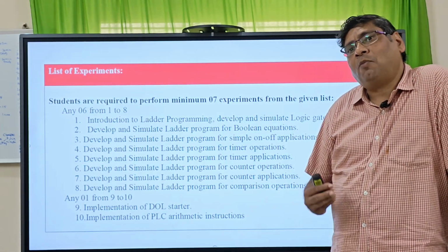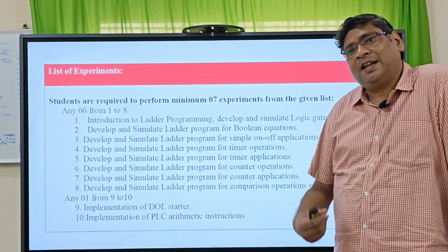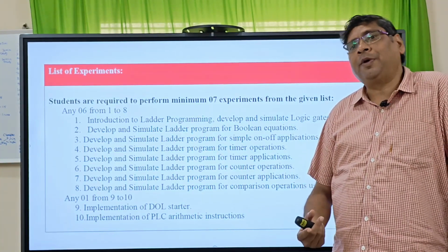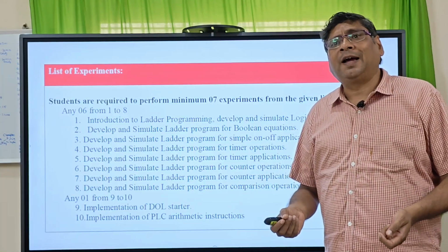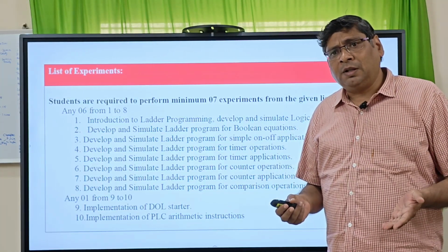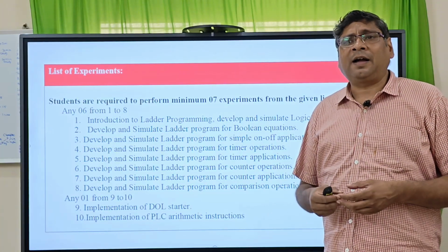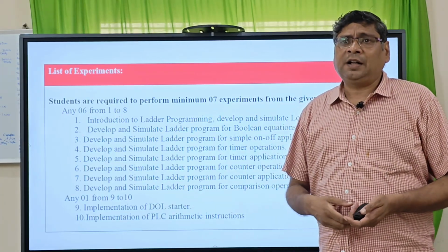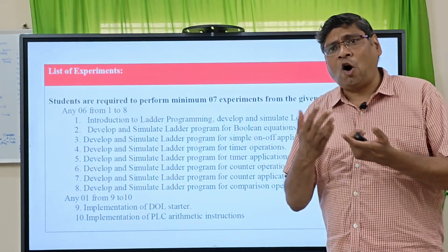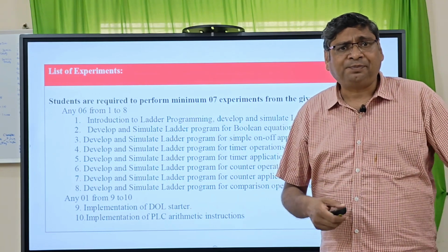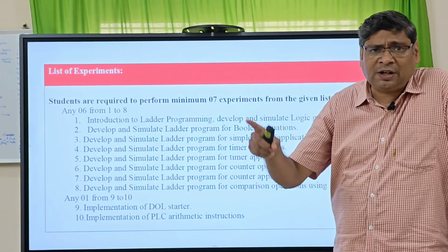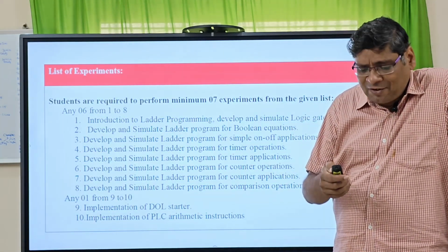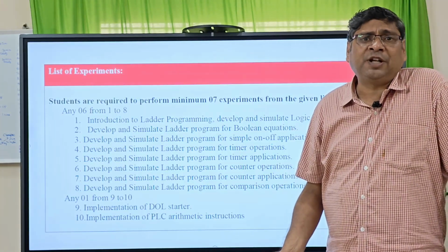We learned what model of PLC hardware you have, and the name of the manufacturer or OEM of that PLC. Then we saw RSLogix, how you open it on your computer, and how you open the program. Then you go to the ladder diagram, where you put the NO, NC and the coil. After that, how you do input addressing, output addressing, coil addressing, and how you use coil latching. We also saw all the 7 gates and the experiments of the gates.